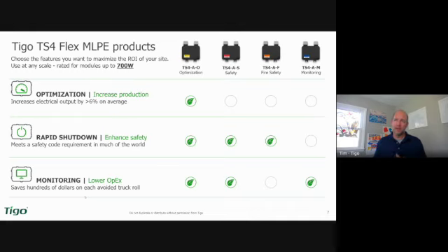But for the installer, having that ability to log into Tigo's monitoring platform, check if a system is functioning well, or if it looks like it could use some service, within the comfort of their own office, log in, see each module, how it's behaving. We have easy ways that help to troubleshoot things. You can quickly identify, oh, it's that module right there. I can tell based off the characteristics that a diode may have gone out, I need to go out and replace that module. So it's a great opportunity to enhance the long-term O&M and reduce truck rolls for the EPCs and developers.